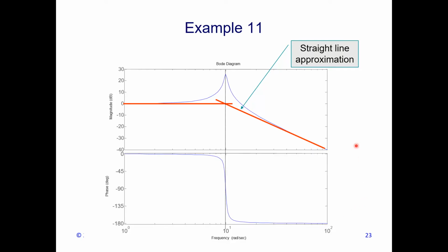As zeta tends towards 0.707, or 1 divided by root 2, we get more of a smooth Bode plot diagram, which is given by that nice smooth curve that we see for the actual Bode plots. We also saw that the resultant equations for MR and omega R can be used to solve for these parameters as well.